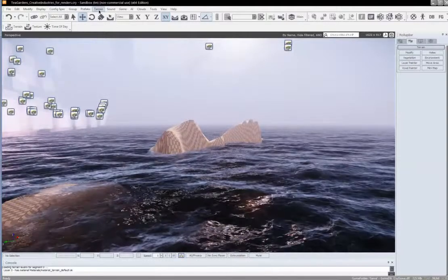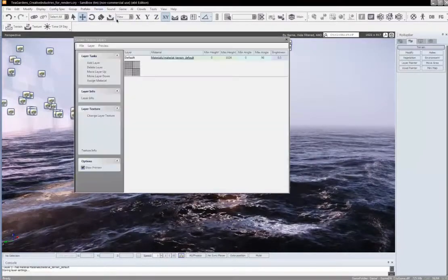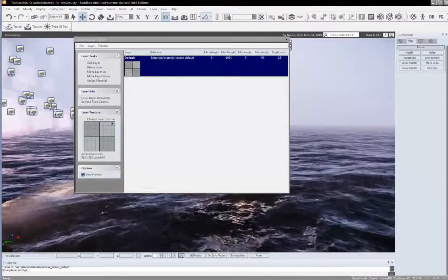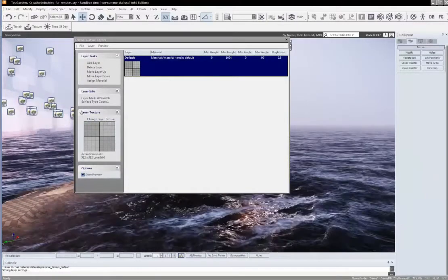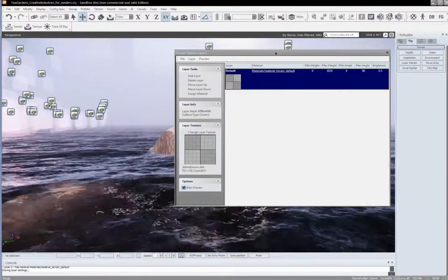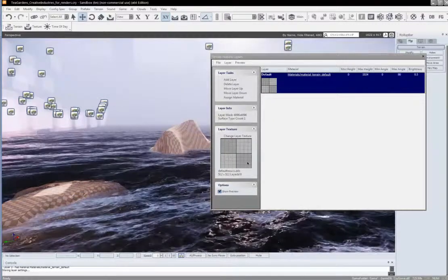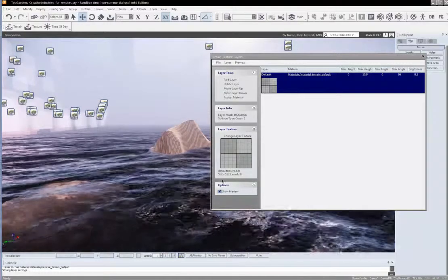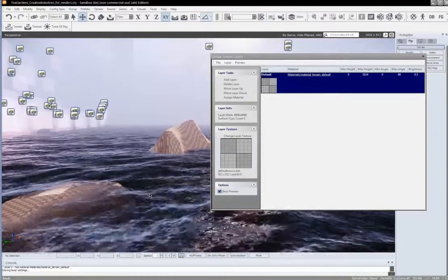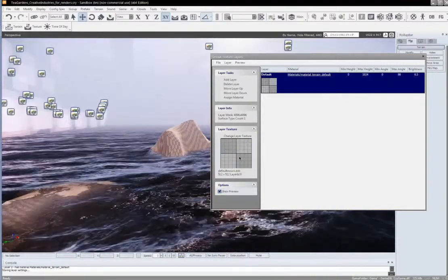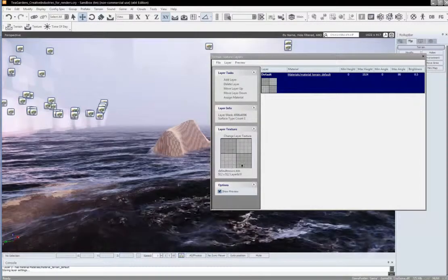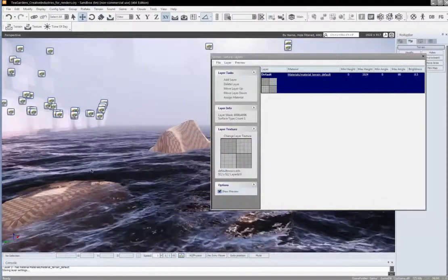Cool. So by default, it's got this checkerboard texture. To change that, you can go up to terrain and then texture. And what it's using by default is this material here. If I click on this, it comes up with this terrain layer texture, and also it's got a material set here. They do a couple different things. So this big image here is going to be over the whole map. See how it's 512 by 512? That's the size of the whole terrain layer. So you can get maybe a Google Earth view of a city or something, and then put it in here, and it'll put it over the whole map.